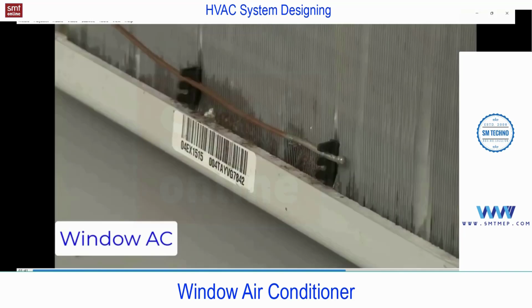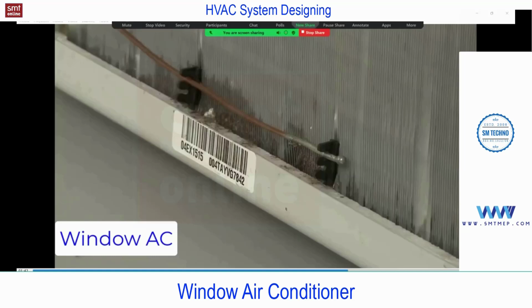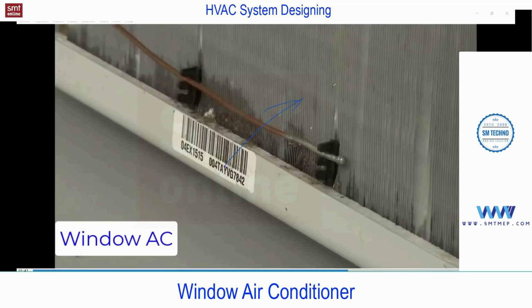The sensing bulb or electronic sensor, you see, this is important. The sensing bulb, you will find when you remove the front panel, is before the evaporator. This is related to the evaporator side. So when the suction takes place, the air will pass through this, and you see these strips are fins, and in that you'll find the coil. So this is a cooling coil. The suction from the room passes through this, and continuously this sensing bulb will monitor the return air temperature.